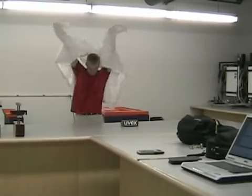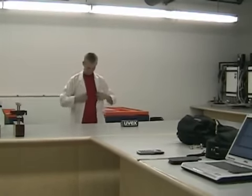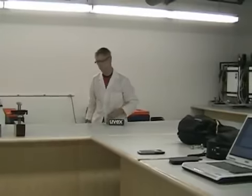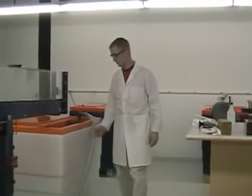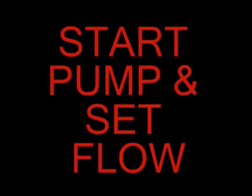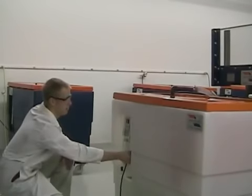Protective clothing is a good idea, but not required for this exercise. Before we start the flume, the hoses must be checked for loose connections to prevent leakage. We can now start the pump and set the flow rate.